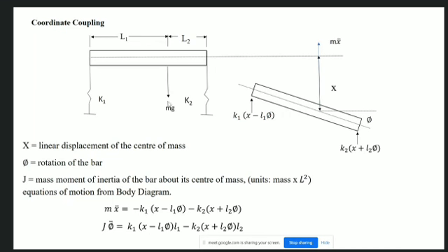So if these two lines coincide, the downward force and the upward reaction, then it will purely undergo translation, because then there is only uniform deformation in the two springs. Though the stiffness is different, the deformation will be the same, and then the bar will undergo a translation.